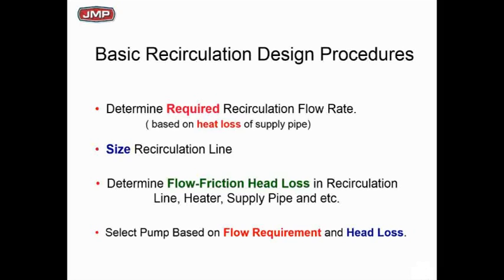Is it going to be 3/4 inch, 1 inch? We've got to know that return line so we can get the friction hit. Go to your Bell and Gossett system size or some friction chart, come up with your head loss for the pump, and select your pump based on flow and head. I repeat, very small pumps, as you will see very shortly.